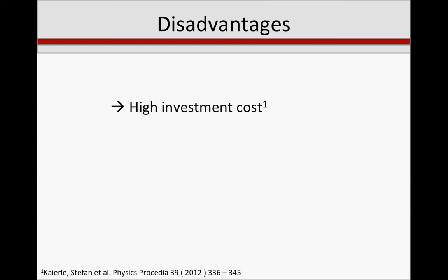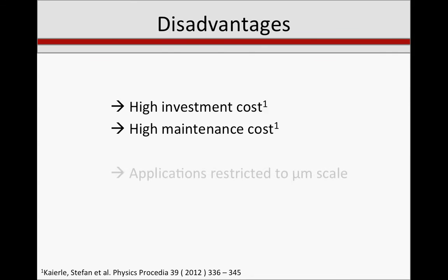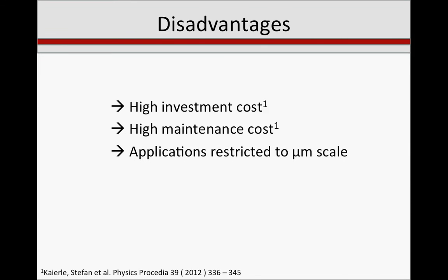It has a couple of disadvantages also, however. There's a high investment cost to obtain the equipment necessary to carry out microlaser welding. Additionally, there's a high maintenance cost associated with this equipment. Applications are restricted to the micro scale, and if a larger scale is necessary, another type of welding will need to be used.